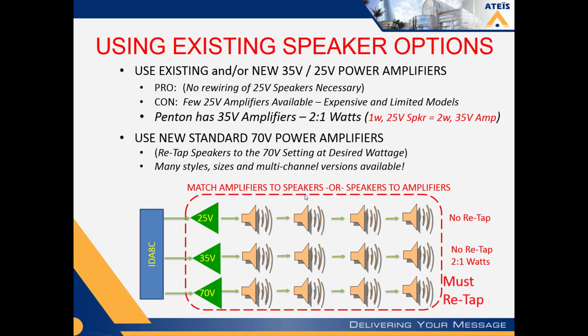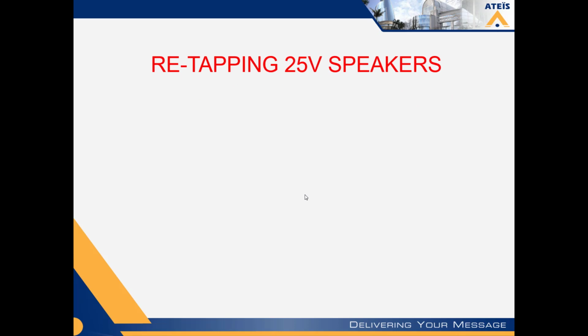Well, you may elect to go with 70 volt, and that's fine. You do not have to rewire your speakers, but you do have to retap your speakers because your speakers are going to be tapped at 25 volts. And so what do I mean by retap?